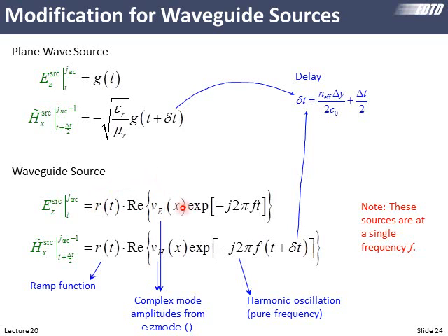We just analyzed the slab waveguide through the cross-section FDTD grid, and we came out with our eigenvectors. So we look at the electric field component of the eigenvectors. For the fundamental source, this looks almost Gaussian, but we could have a second or third order. That's this amplitude function. That's what it looks like in the cross-section. We've also calculated its effective refractive index, so we know how it propagates. We also know that it oscillates in time.